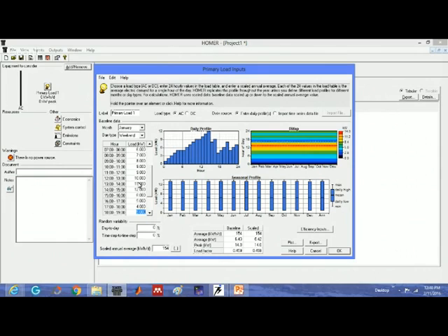See, I have given two days of data here. One is in January: on weekend days a different load is there, and on weekdays a different load is there. This is what I'm calling the winter profile. And in summer, do we have to make two different load curves? Yes, we can give up to so many. You can feed, let's say, 365 load curves.